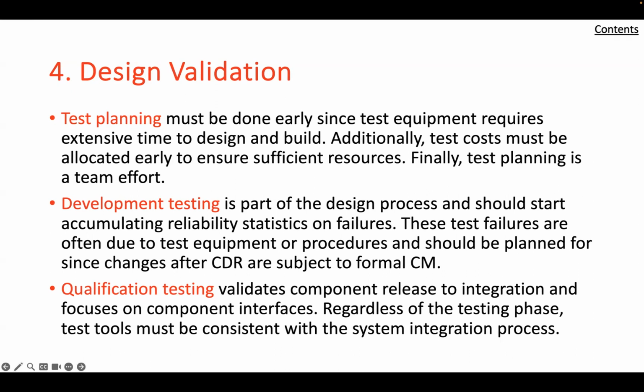Development testing is concerned with validating the basic design of the component, focusing on the performance, especially on features that are critical to the operation within the system or that represent characteristics that are highly stressed, newly developed, or expected to operate at levels beyond those commonly attained in previous devices of this type.